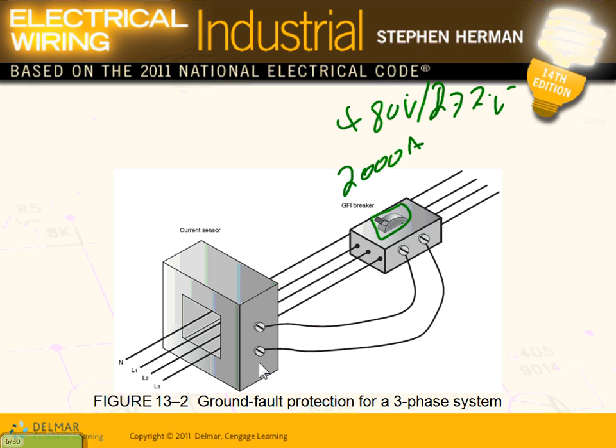If you have a ground fault, they have a sensor, a donut like this. Can you guys see the current that's going through each one of these phases and the current that's going through the neutral? If they have a balanced system, the neutral will be carrying 0. If the system is not balanced, you're going to have a current through the neutral. So this will look at the current in every phase and the current in the neutral, analyze them, and if there's substantial difference between them, this means that phase is actually shorted to the ground. Right? Any one of them.